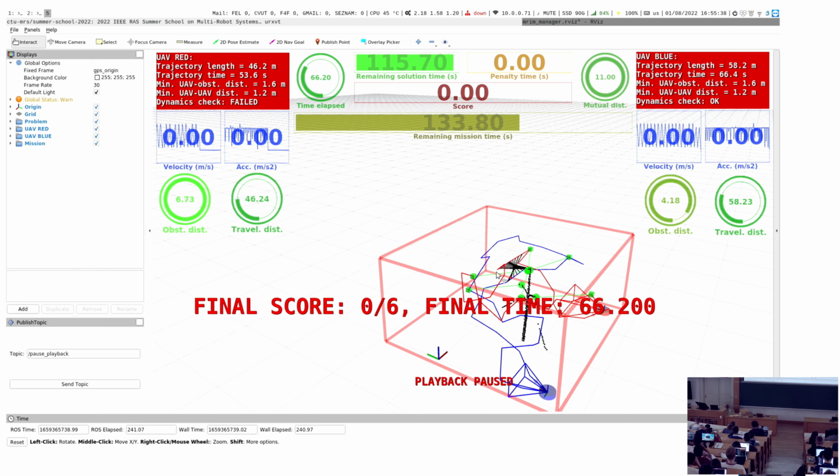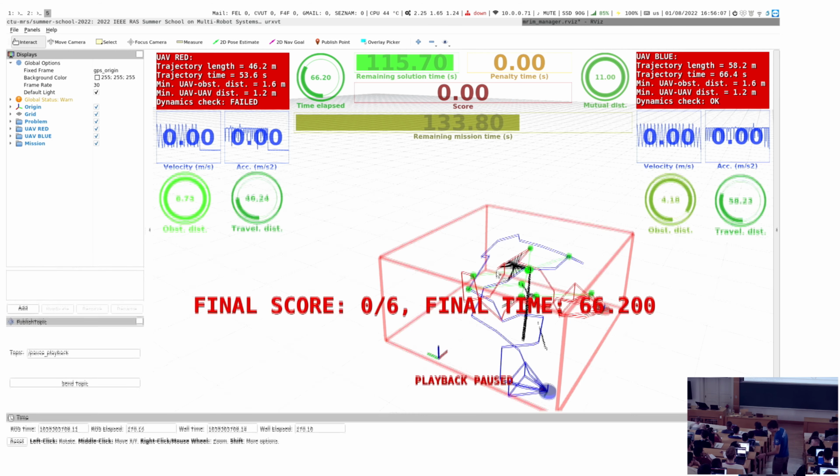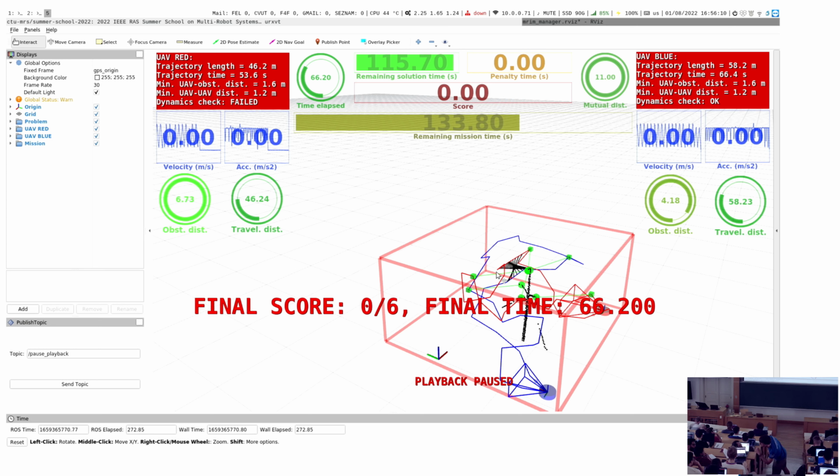It is not that true. Implementation-wise, MAVROS is sort of hard-coded in the system right now. So we are dependent on MAVROS, and it would take some time to cut it out and swap it for some other system which communicates with PIXHawk. And I have it as a future to-do to pluginize this hardware layer. So MAVROS would be one of many plugins which you could use for communicating with underlying embedded hardware. But technically, it can be anything, like BLHeli, whatever, some other systems. No DJI. DJI is bad. Yeah.